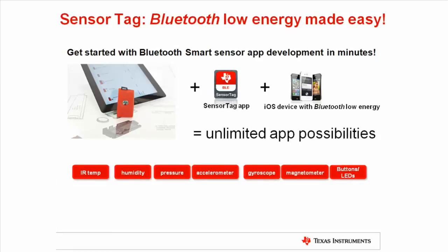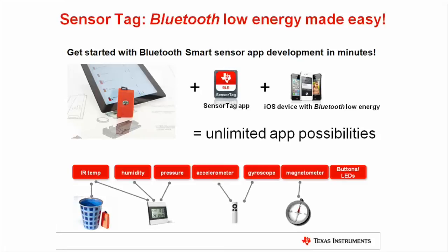To illustrate how the sensor tag can be used to demonstrate an accessory idea, imagine a weather station that uses the phone as a display. To test this idea, use the sensor tag app, enable the temp sensor, humidity sensor, and barometer, and show the results on the phone.